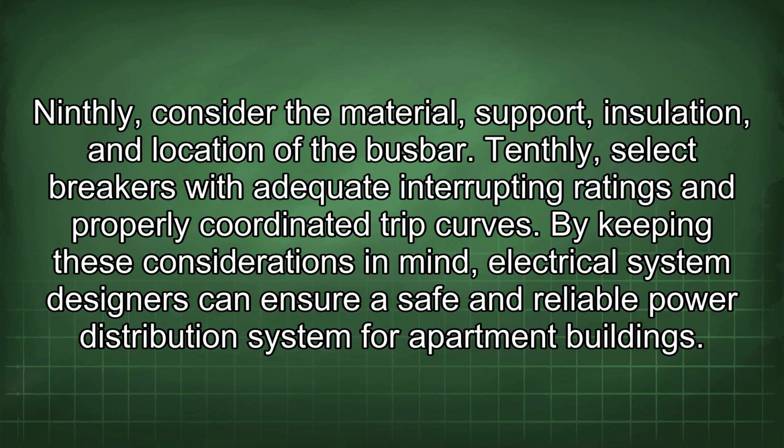Ninthly, consider the material, support, insulation, and location of the busbar. Tenthly, select breakers with adequate interrupting ratings and properly coordinated trip curves. By keeping these considerations in mind, electrical system designers can ensure a safe and reliable power distribution system for apartment buildings.